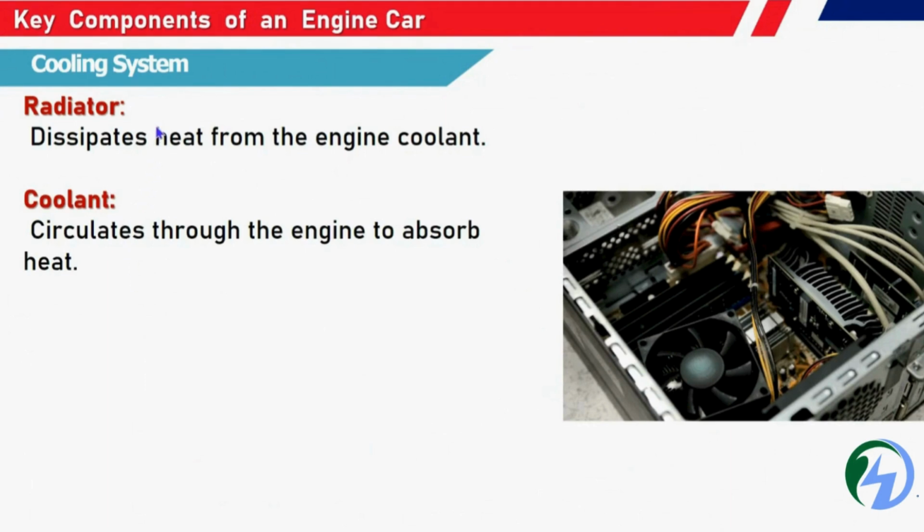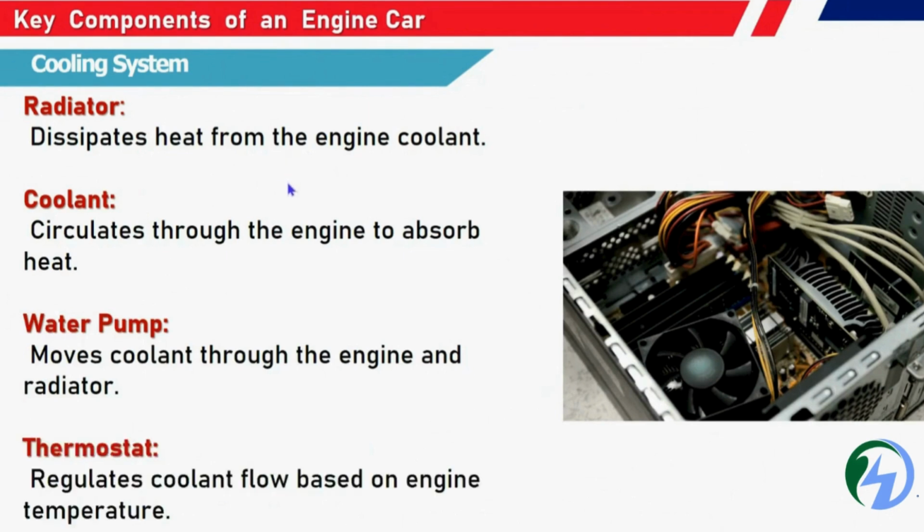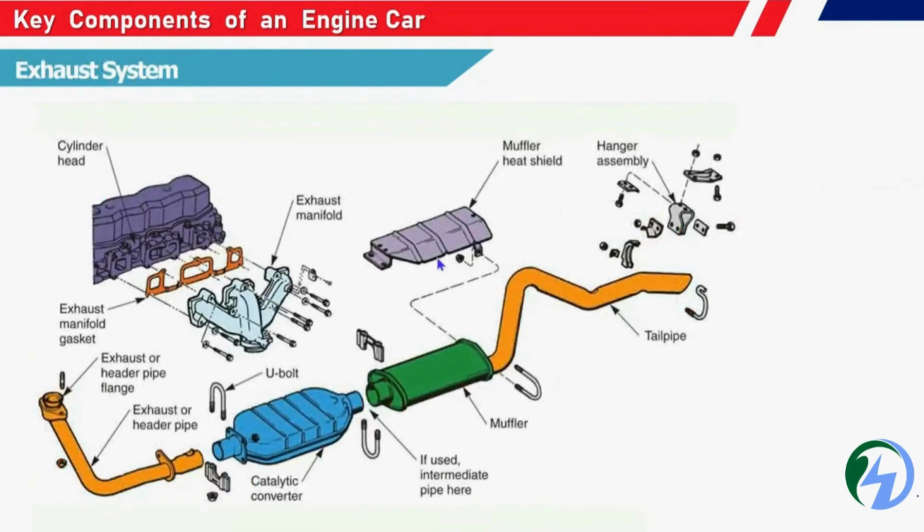So the radiator will remove the excess heat from the engine coolant, and coolant is the one that circulates through the engine where it will be heated up. The water pump moves the coolant through the engine and the radiator. The thermostat will regulate the coolant flow based upon the engine temperature. So that's how the cooling system plays a major role.